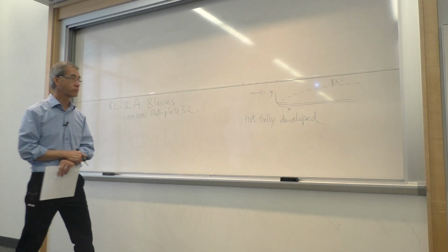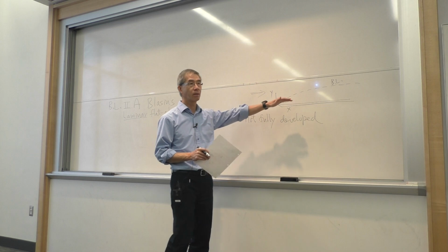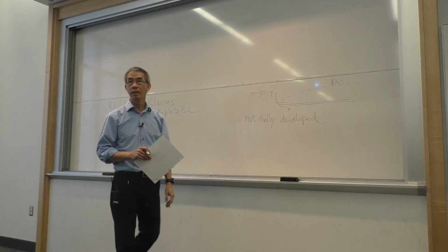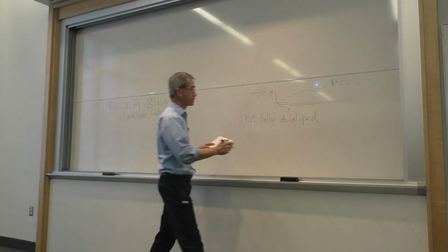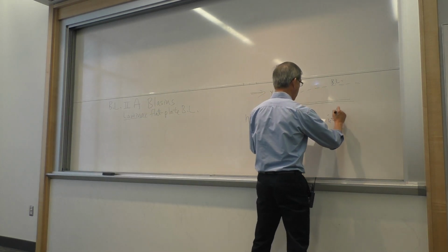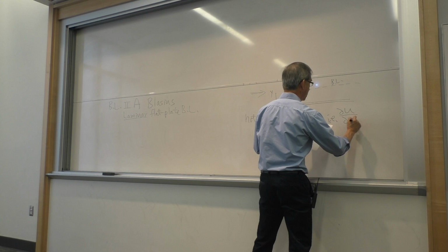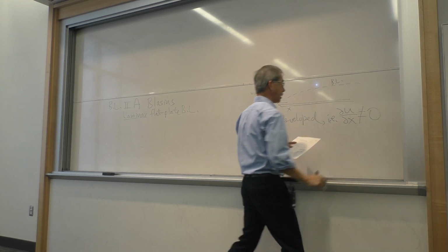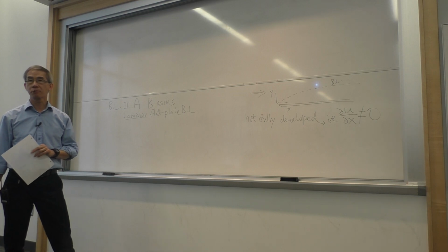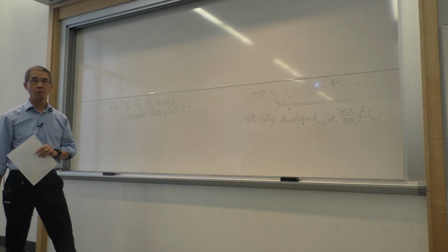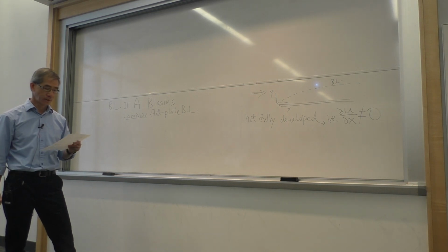The boundary layer will continue to grow as the plate gets longer and longer. Because of that distinction, this is not a fully developed flow, and hence a lot of the simplification we did with the homework, that anything with respect to x, the derivative is zero, is no longer true. Just that small subtlety makes this problem a whole lot more challenging and difficult.